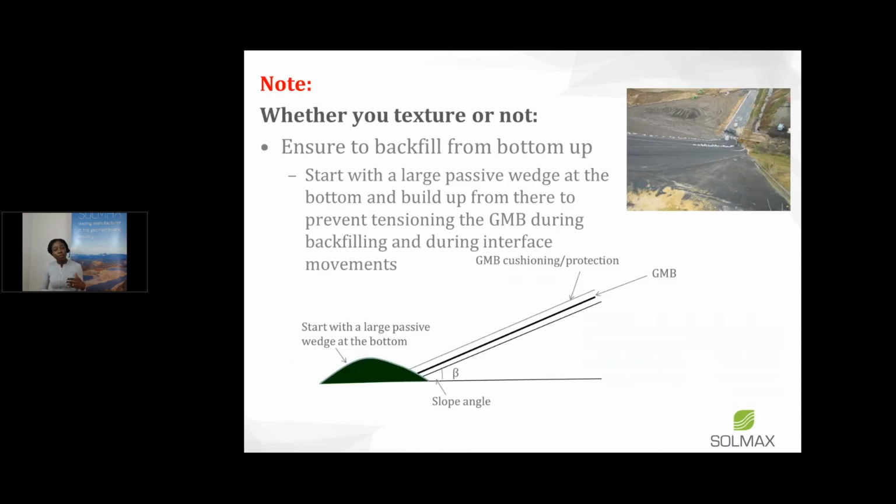I'd like to state first that whether you texture or not texture a geomembrane, you have to ensure that when you backfill over the geomembrane, you backfill from the bottom up. I got a few emails from renowned industry experts who said, one thing you have to mention in this webinar is, regardless of whether you texture or not texture, let them know that they have to backfill from the bottom up.